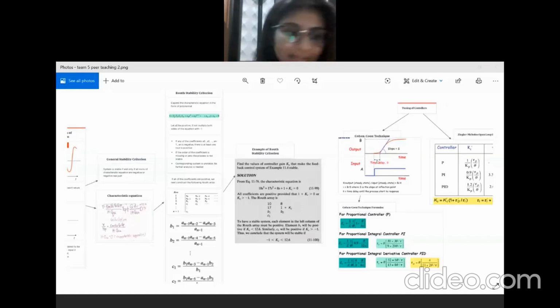There is time delay. Time delay is basically the time difference between the change in controller output and the intersection of the tangential line and the original level of the process variable, which is this. And the slope is the slope of the process variable at the inflection point. The inflection point is labeled as B in here. The inflection point and slope are used in calculating the tau.